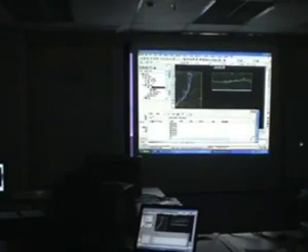So this is very different from Land Desktop and Civil Design. Even though you've never used Civil Design, just to let you know, Civil Design is kind of like Land Desktop. When anything has been done, you need to reprocess everything. You need to reprocess what the sections are, where the position of the new horizontal alignment is. In this case, you just need to move and everything's updated. So at least you can be very sure in this sense that it is the latest information.